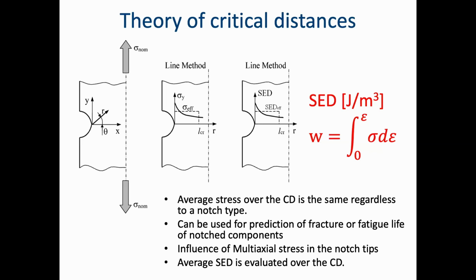With this assumption, it can be used for prediction of fracture or fatigue lifetime of notched components. We try to use both the axial stress and the strain energy density, because it can also cover the influence of multi-axial stress and so on.